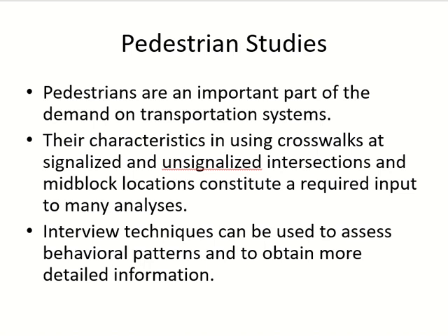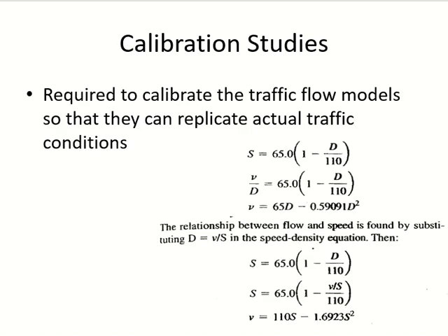There are many pedestrian bridges which are just built using thousands of dollars, but nobody is using them. So you have to do some studies to know what should be done at that location. And obviously it's a matter of choice, right? I cannot know why people want to cross from their location until I ask them. So you have to do some pedestrian interview studies as well.